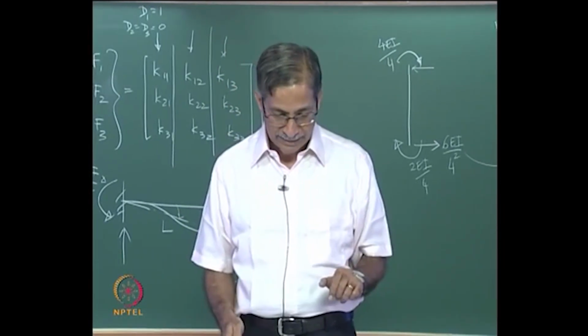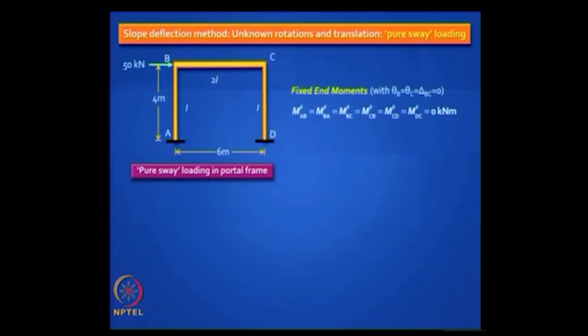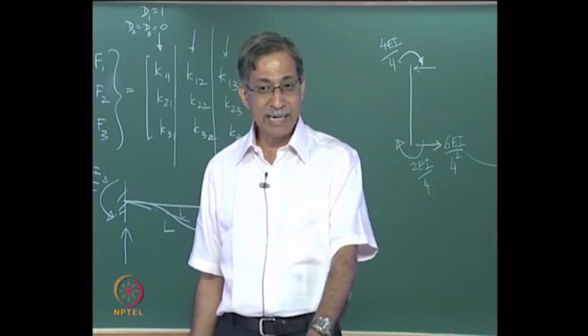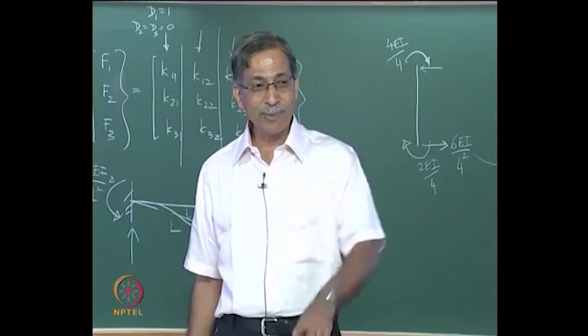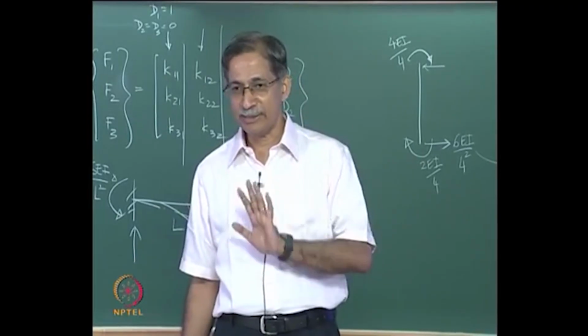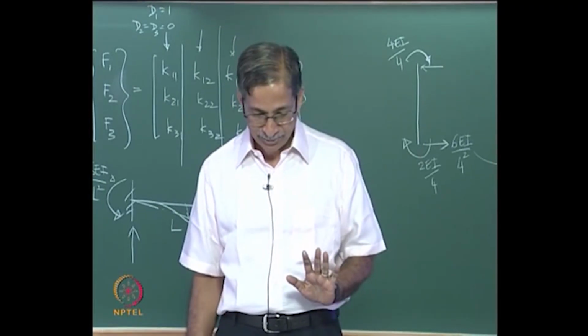I will conclude by dealing with one last problem of pure sway. You have this frame subject to pure sway, okay. How do you solve this problem? Are there any fixed end moments? No fixed end moments. Deflected shape will look like that. Remember we did an approximate analysis when we did portal method, cantilever method. We don't do anything approximate now, we do the exact solution.